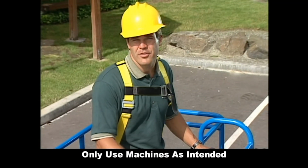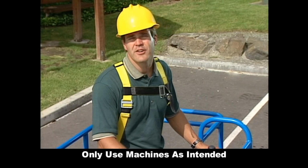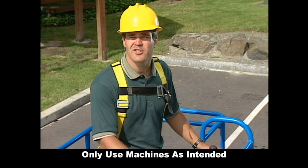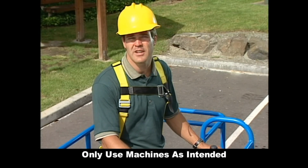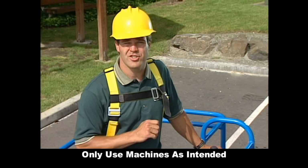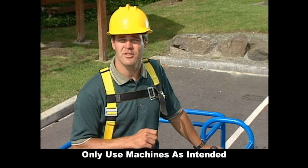Only trained and authorized personnel should be permitted to operate a machine. If more than one operator is expected to use a machine at different times in the same work shift, they must all be qualified operators and are expected to follow all safety rules and instructions in the operator's safety and responsibilities manuals. That means every new operator should perform a pre-operation inspection, function tests, and a workplace inspection prior to each work shift.